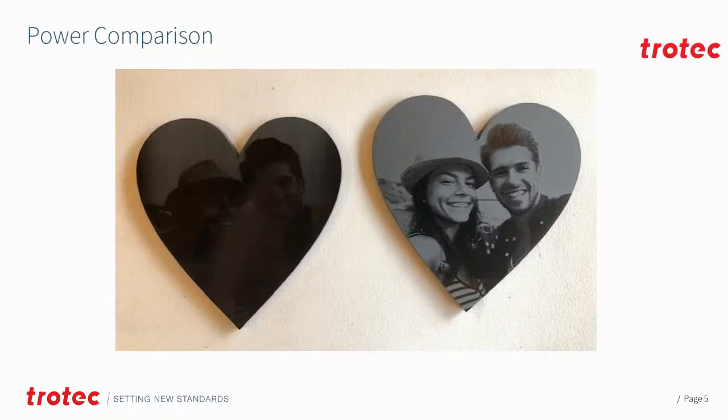So if we have a look at this little example here, we've got a nice comparison of 2 different powers. Here we have something that is quite clearly underpowered, so we can't see much of the image coming through at all, and here we have something that's probably slightly overpowered. The reason I say that is if we look at the contrast between the upper surface and the hat, you can see that we cannot see any definition. Again, that's because too much power makes all of those pixels start to overlap, and we end up with a worse quality engraving.